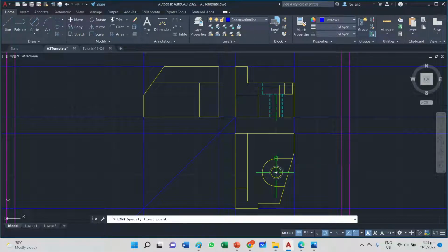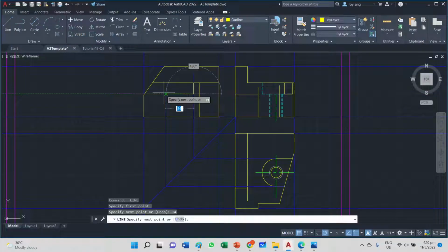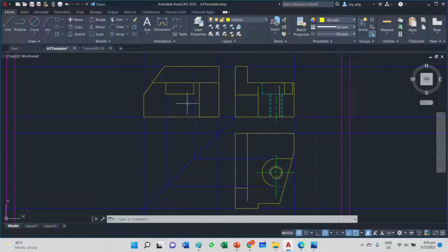What we can do is we can make use of projection lines. So I'm going to use my construction lines and tap it across, and then more construction lines and tap it across. Okay, and then I'll start off with my outline, and I know it goes down by 14 millimeters, and it goes across and it goes up, right? And that's my cutout. Okay, that's my cutout, and I'm going to delete these lines away.